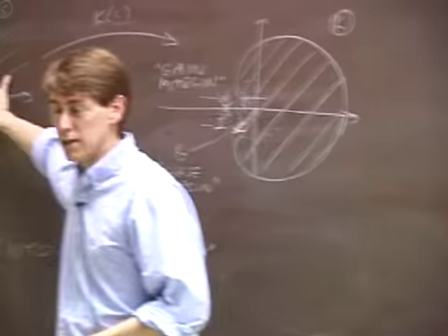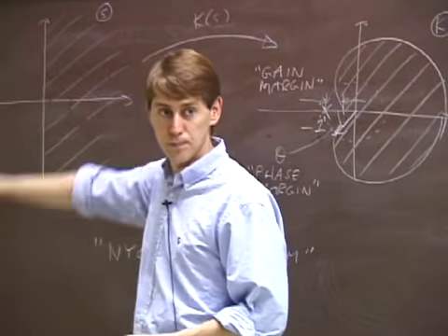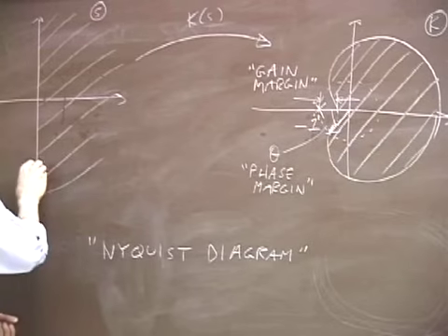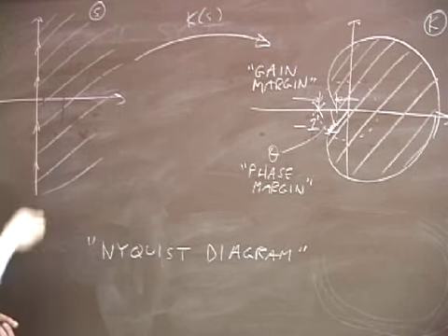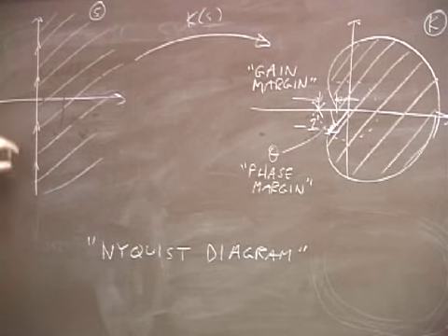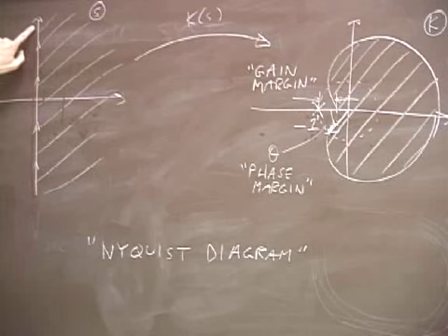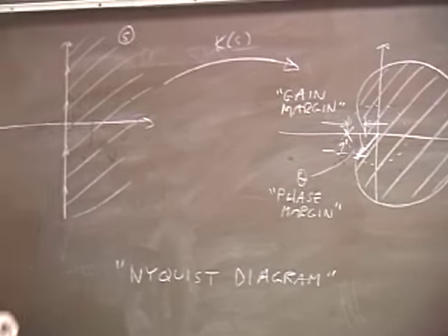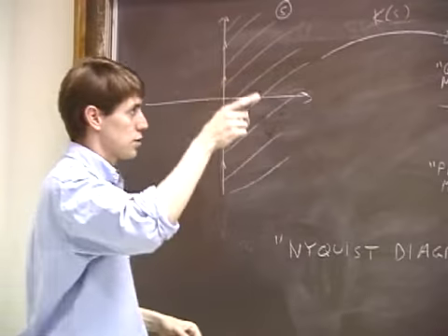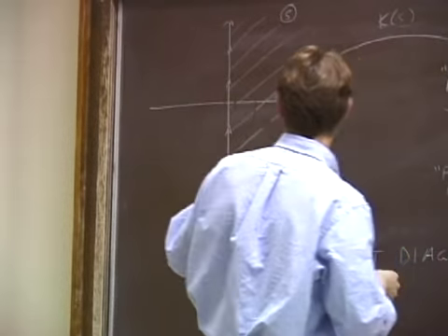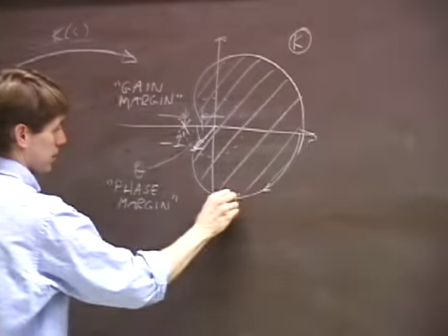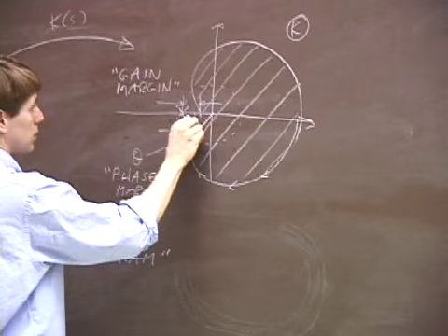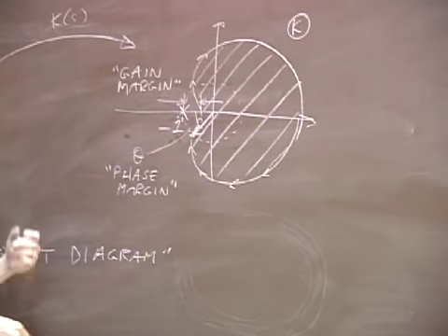What you really do, actually, is you don't operate at a point in the right half of the S-plane. You just operate on the imaginary axis. And there's a theorem, in fact, it may be the conformal mapping theorem, I don't remember. Some of you who are more mathematical than me may know which theorem I'm talking about. It says if you run a parameter up the imaginary axis, then it preserves orientation once you map it into the K-plane. So all you have to do really is map this line, and this line maps into the boundary. And in fact the direction gets preserved.